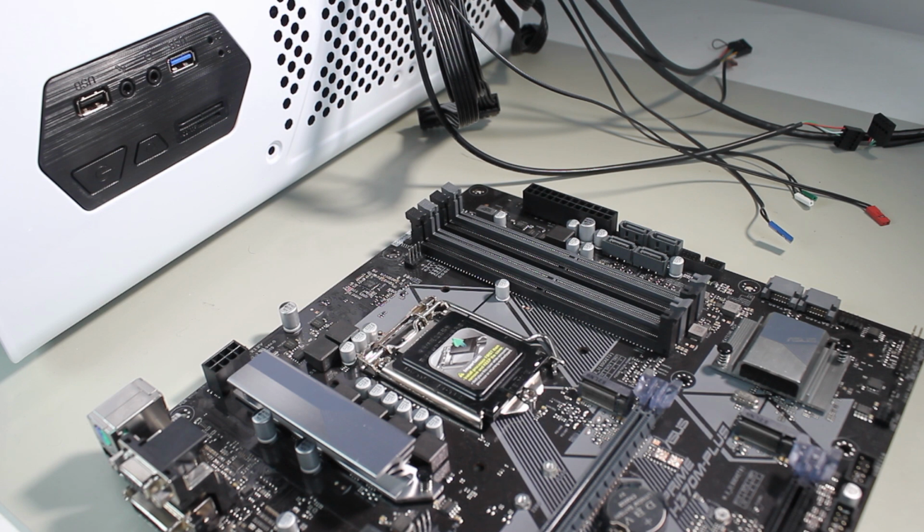The first is the larger 20 or 24 pin connector, otherwise known as the P1 connector. Older motherboards use a 20 pin connector, but that was found not to deliver enough power, so an extra 4 pins were added to provide the extra power. Your power supply may have a single 24-pin connector or a 4-pin and 20-pin connector that can be combined together or broken apart. Even if your connector cannot be broken apart, you can still plug a 24-pin connector into a 20-pin connector. The extra pins will just hang over the side of the connector. You will only find a 20-pin connector on older motherboards.